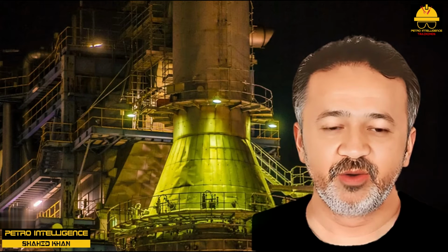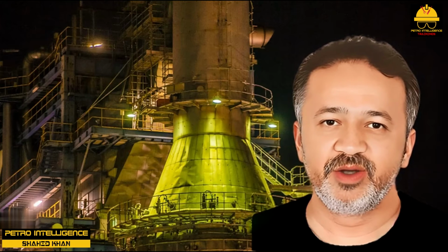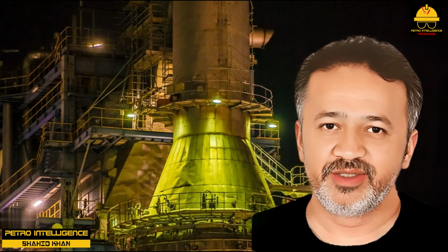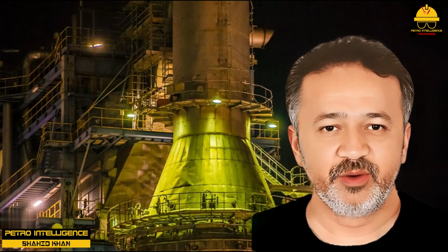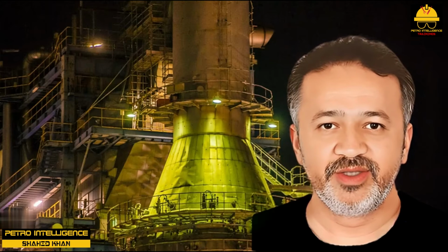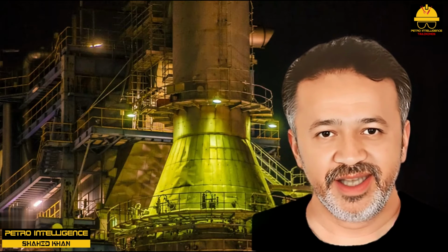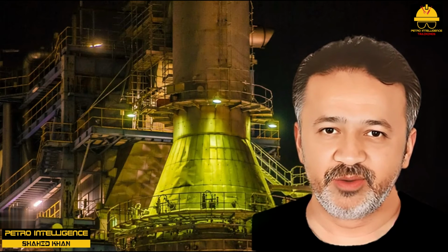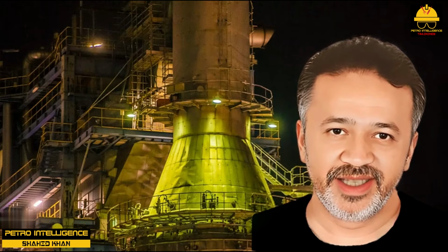Secondary combustion, or afterburn. In the preceding paragraphs we discussed how operation without enough combustion air, on the wrong side of the point of absolute combustion, leads to inefficient combustion of fuel. Apart from the fuel wastage, there is another important, disturbing and frequently occurring problem associated with this bad mode of operation. The products of incomplete combustion of the fuel, and in more severe cases even the unburned fuel itself, flow with the flue gas up through the convective section and up the stack.